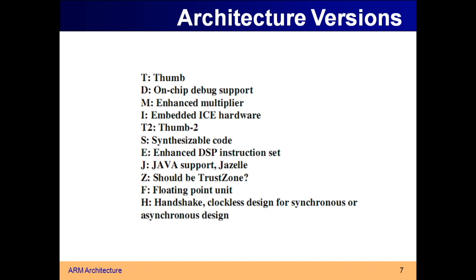Whenever you need high performance, you can use the ARM instruction set. Whenever you need more code density, you can go for the Thumb instruction set. How are you increasing the code density? Because your instructions will be only of size 16 bits. So instead of accommodating one 32-bit instruction, you can accommodate two 16-bit instructions if you are using the Thumb instruction set.